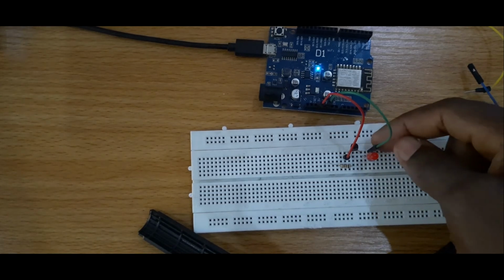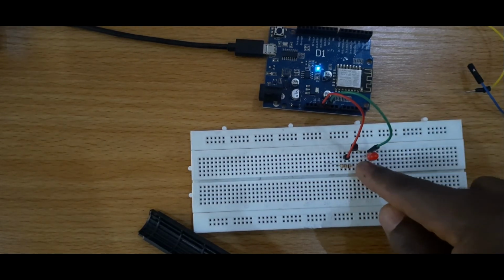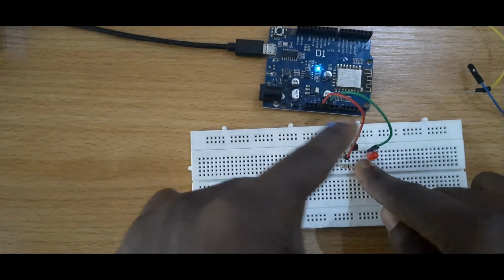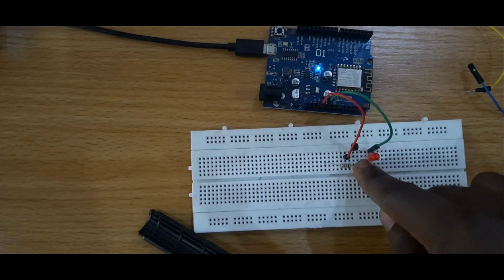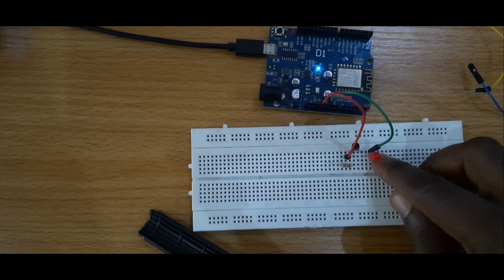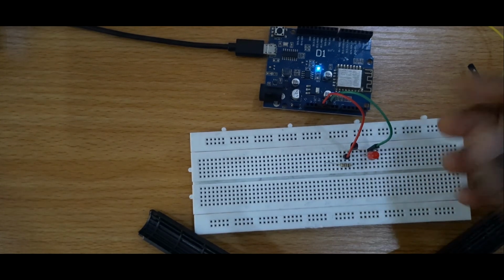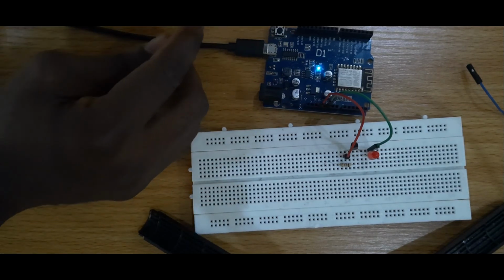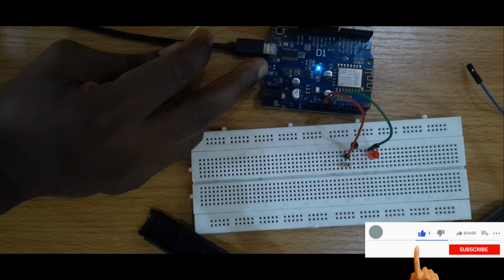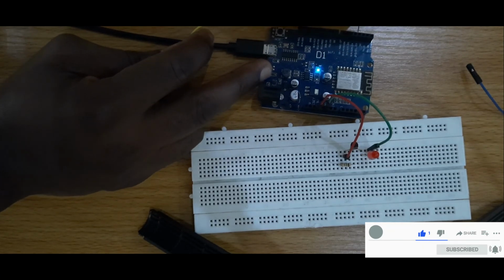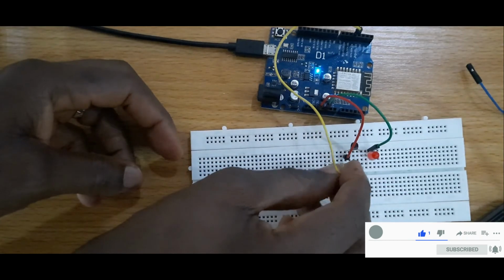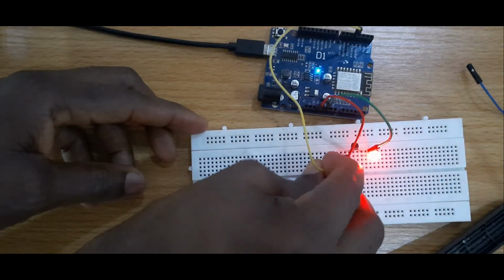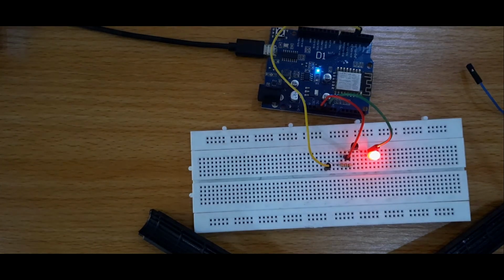I have the emitter part connected to the positive side, because remember I took positive from there and I'm expecting it to flow to the other side of the Arduino pin. So the positive should connect to the emitter. Then I have the negative, that's the ground, connected to the ground pin. The last part I need to connect is my pin 4. That's what I used, D4. So it's connected now. I'm going to connect that to the resistor, and you can see it works. So that's how to connect it.